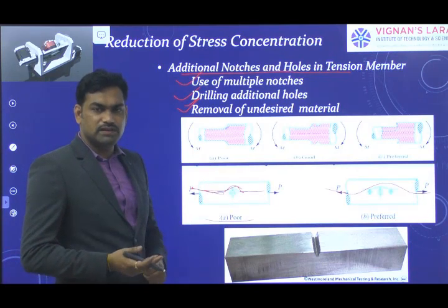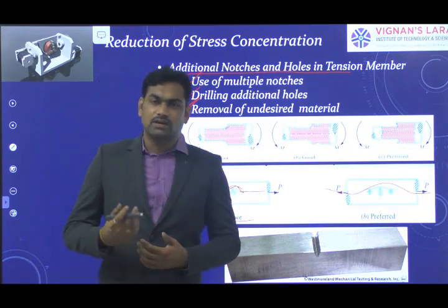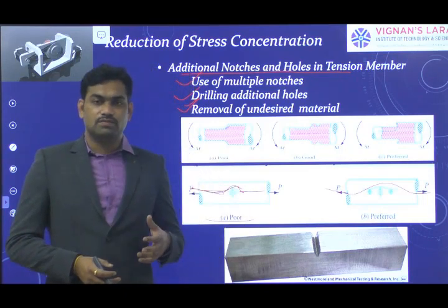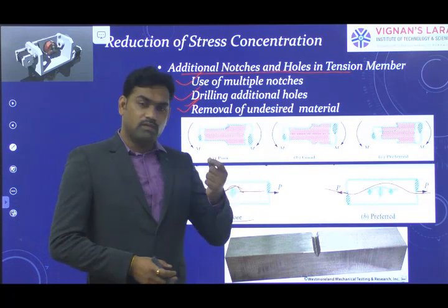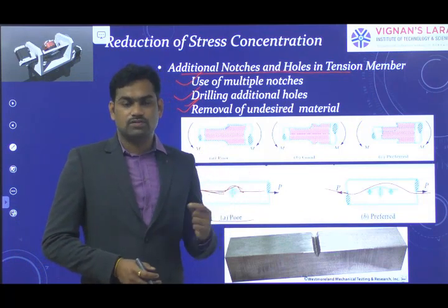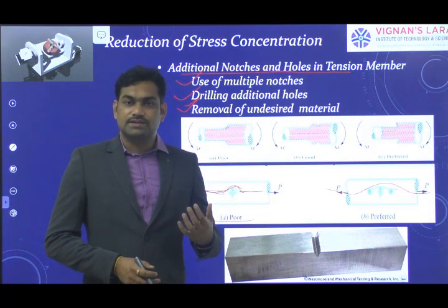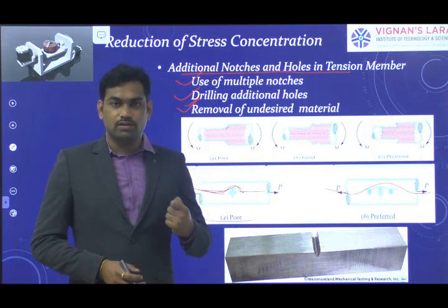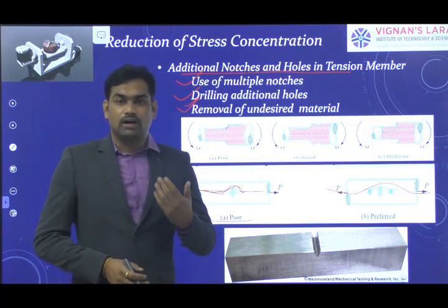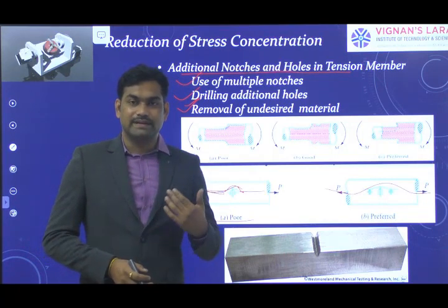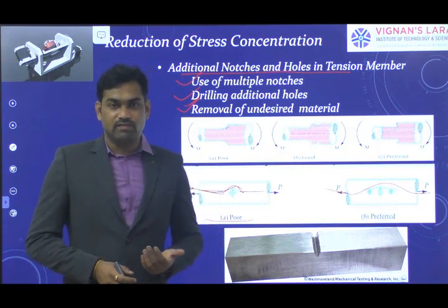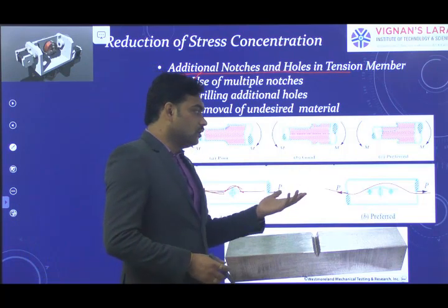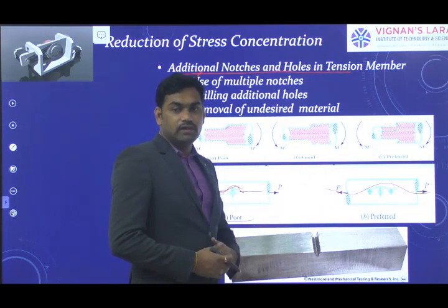There is one disadvantage. Whenever we drill holes, the strength of the material is going to reduce by removing material, but you can provide small diameter holes, which does not matter, so that the stress concentration in the component is going to reduce. That leads to an increase in the life of the component, in order to avoid failure.